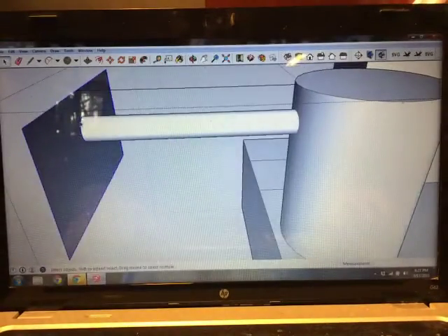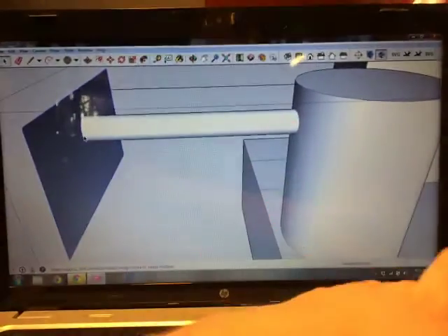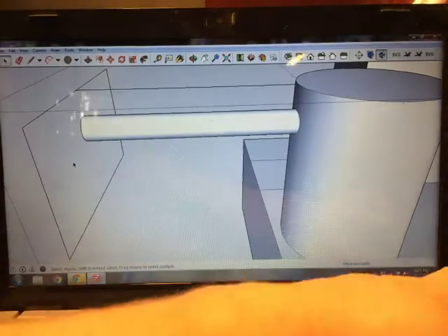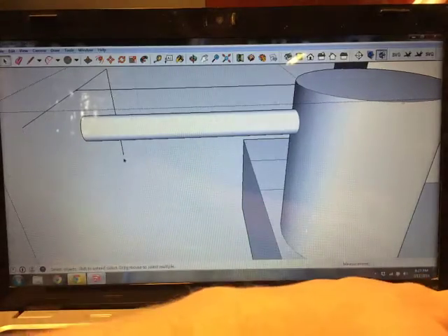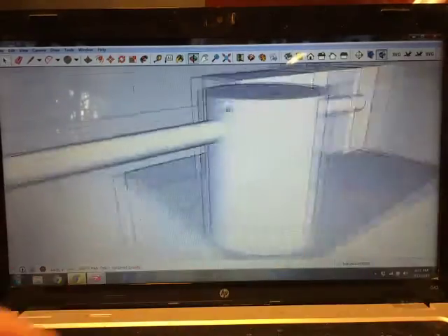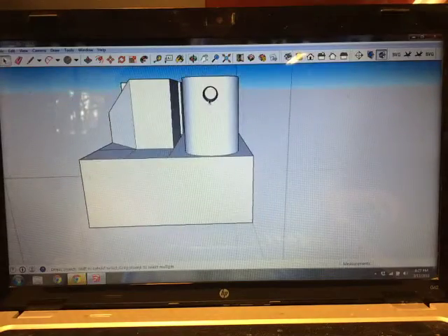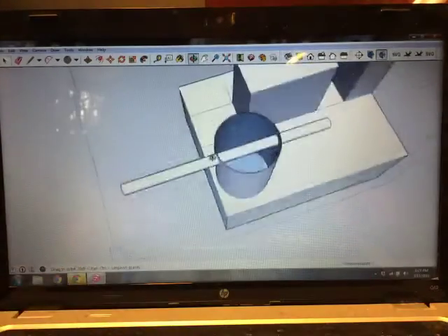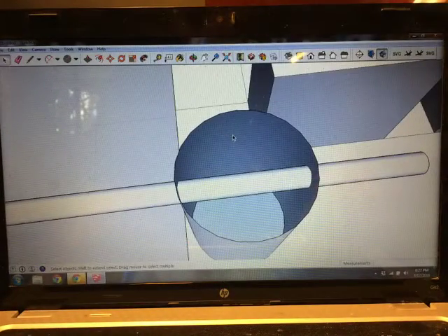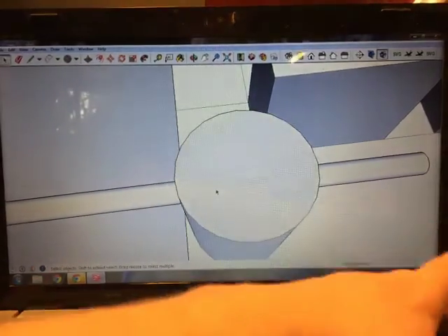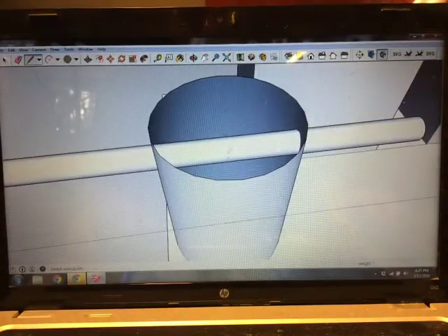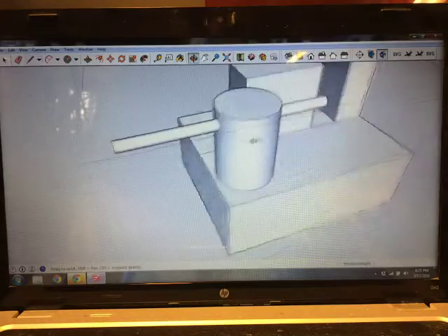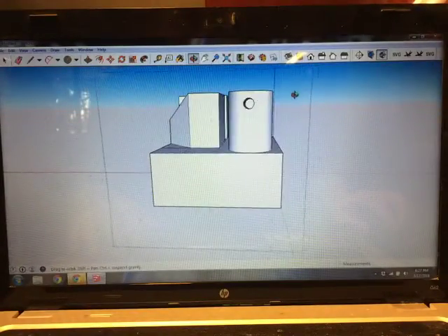Now, if I deleted this, notice I'm deleting the end. I would lose all these faces in here, so that wouldn't be good. Control Z. But if I just delete the face, and then you may have to do a few little select all kind of things. And this has that cylinder face right there in it, so that's not going to work, right? Delete this and look at it. If you want that face back on, you can either Control Z, or there are other ways to put faces back on there. A lot of times you can just repeat a segment, and it will try to fill in anything that segment might have completed.